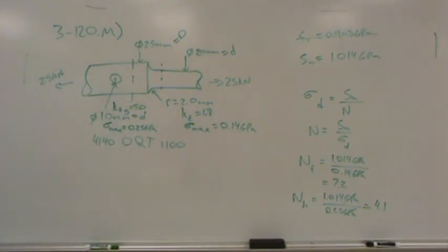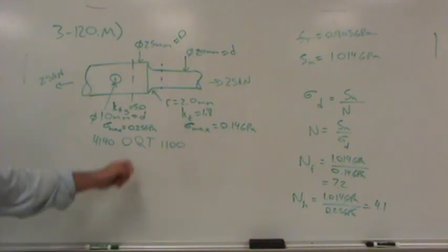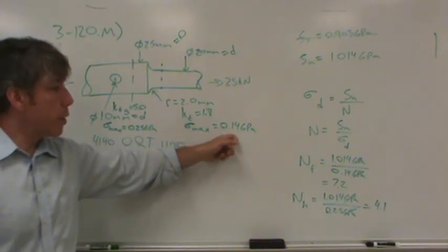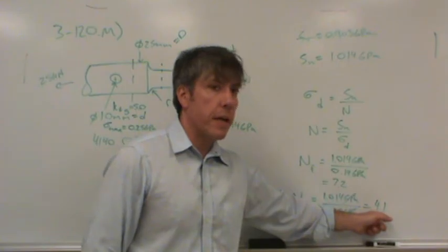So it'll fail at the hole first because it's got the smaller factor? Yeah, you can say it two different ways. It'll fail at the hole first because it has the higher stress, or you could say because it has the smaller factor of safety.